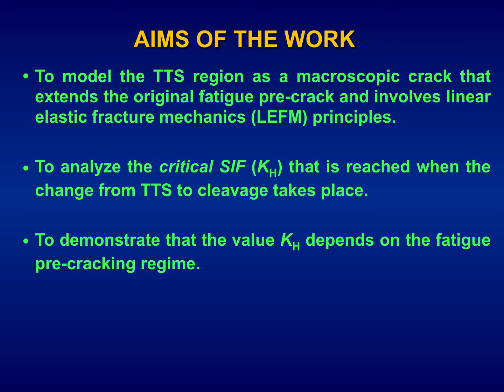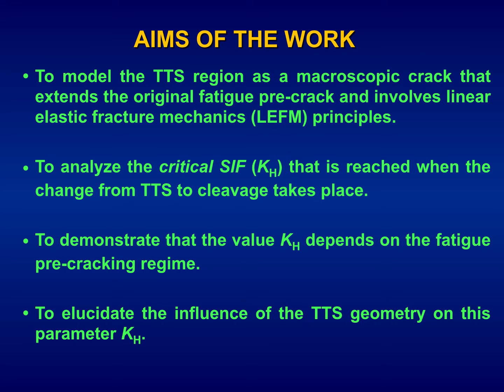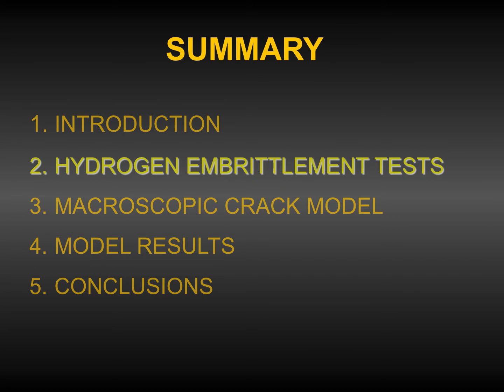To demonstrate that the value KH depends on the fatigue pre-cracking regime, that is, on the level of fatigue pre-cracking, and to elucidate the influence of the TTS geometry on this parameter KH, the critical stress intensity factor under hydrogen-assisted cracking conditions. Let's go to the second part, hydrogen embrittlement tests.